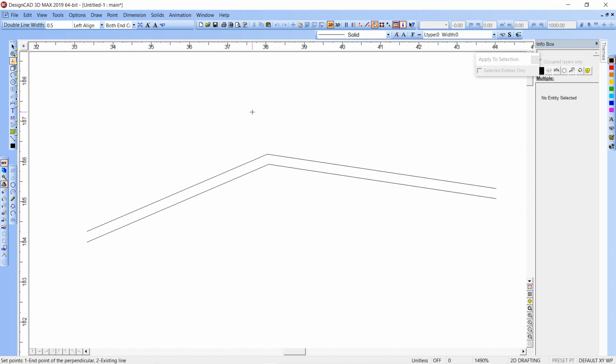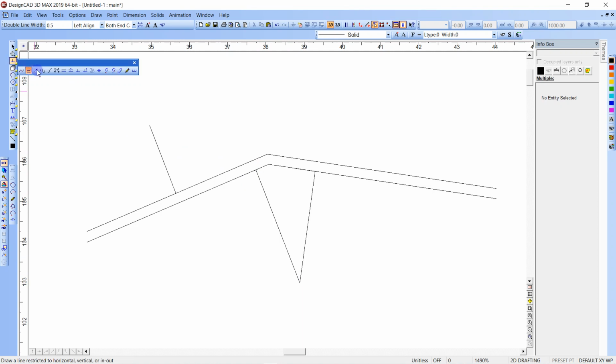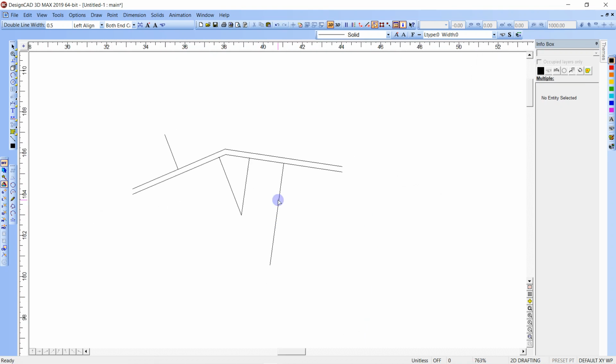Okay, perpendicular, so it'll draw me a line perpendicular to that line, and from anywhere, let's say right here, it'll just go perpendicular to that point, right? So from anywhere, it just draws a perpendicular line, V, do the same thing. And then the other one is, it's interesting, they give it to you from, but they require you to, with a distance. So perpendicular from, Control K, and it gives me a length of 5 away.